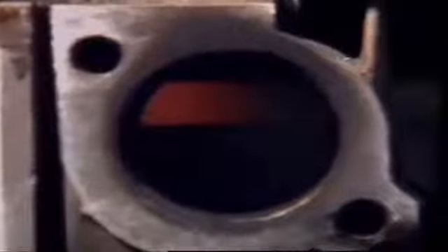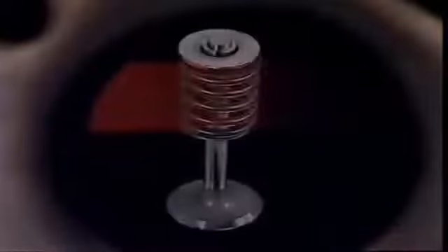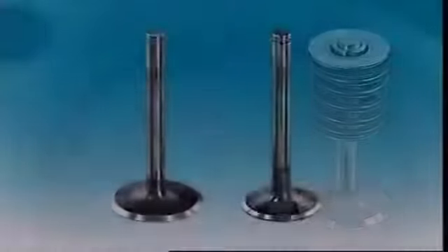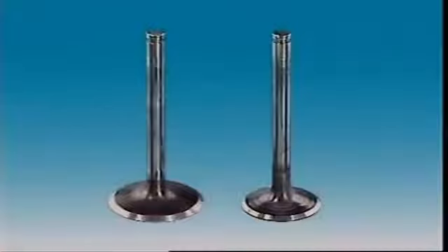Valves experience enormous stress even in normal conditions. In a four-cylinder car driven at around 90 kilometres per hour, each valve opens and closes about 30 times a second. Exhaust valves withstand huge temperatures, and they can become red hot. A valve must not soften at high temperatures. It needs good hot strength to stand up to being forced against the seat and to prevent tensile failure in the stem. It needs good fatigue properties to overcome cracking.